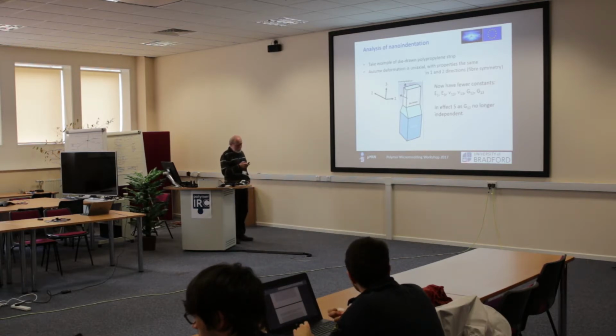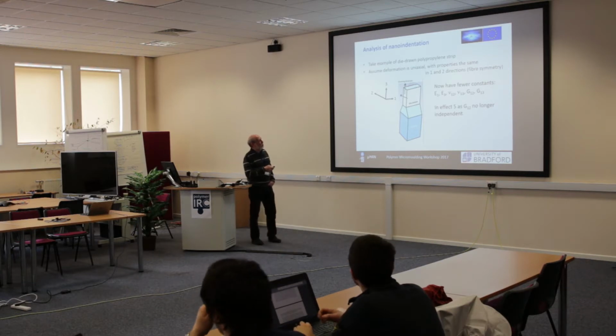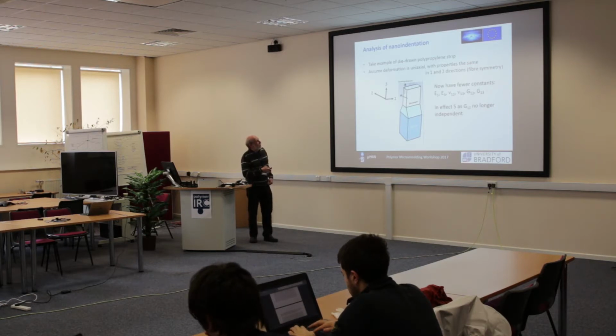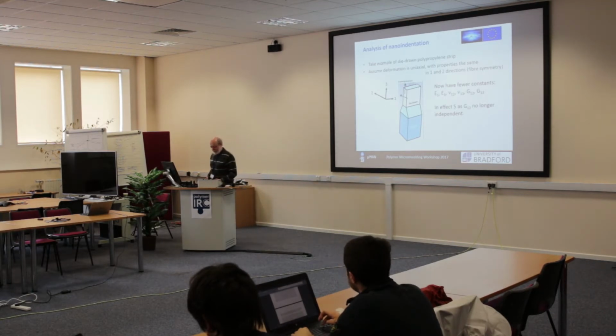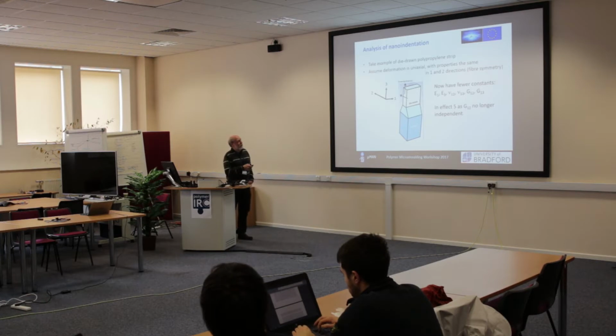So now we're slightly crossing our fingers, and we assume that the 1 and 2 directions have the same properties. So we've got symmetry here. The 1-2 plane is basically isotropic. So we've got that kind of symmetry. This will certainly be true if you've drawn a rod, but you may get some restraint when you're drawing along this direction. So the effects will be small. So we can analyse this reasonably accurately by assuming we've got this uniaxial type of deformation.